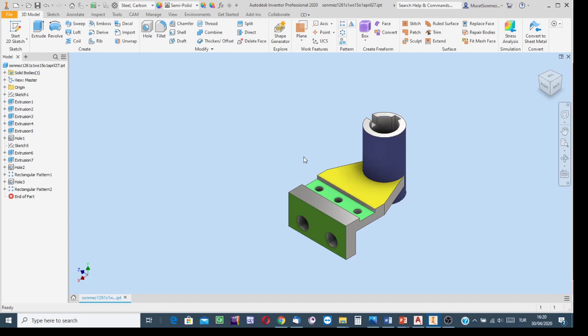Which method you like? The classical method: indicate the surface, or, if indicating more than one surface, click with the Control key pressed, and then right click the mouse and choose the properties option. In the other method, click on this button to bring this dialog to the screen, select the color option and select the surface, and then moving the square over the diamond changes the color density. Okay, in the Inventor environment, yes, these are the facilities for surface painting, for having a surface effect, a coating.